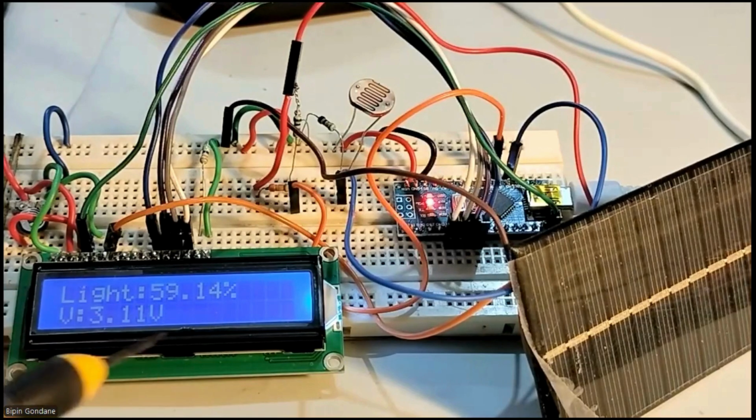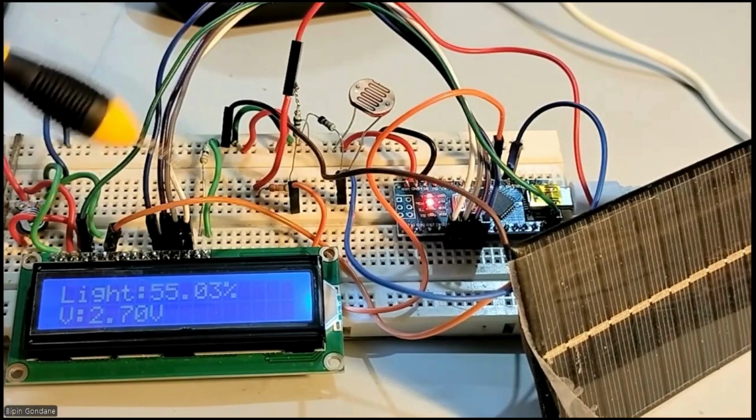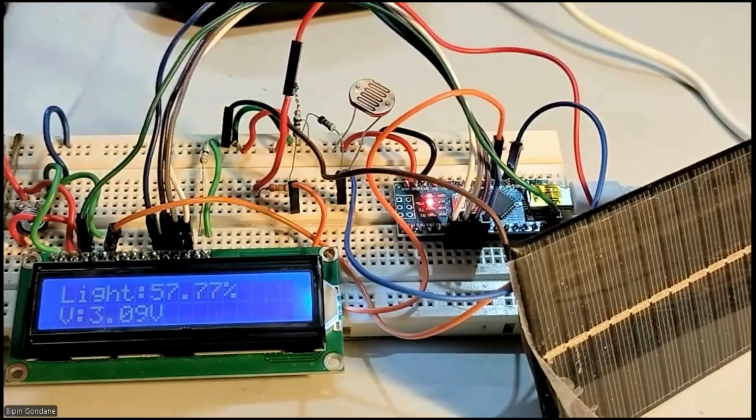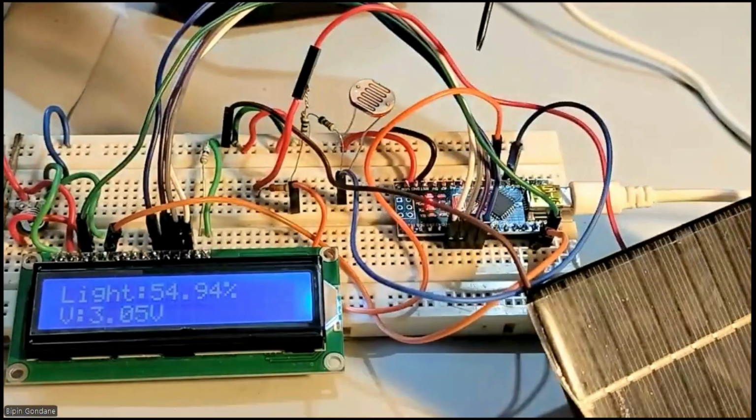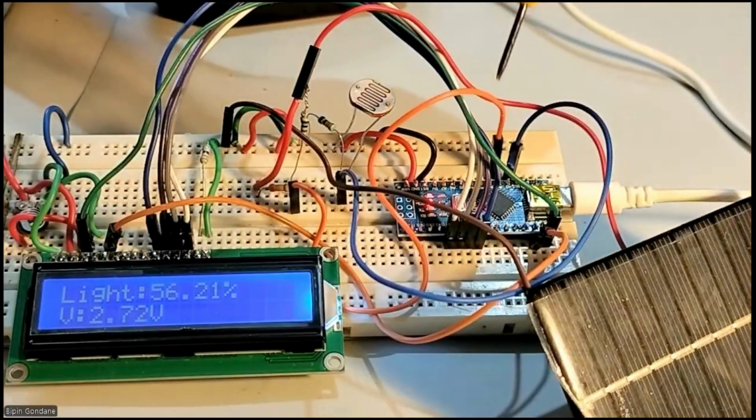Okay, this is my 16 cross 2 LCD with 16 pins. Pin number 1 is ground. Pin number 2 is supply, that is 5 volt. And the third is connected to the potentiometer center point, that is for controlling the contrast of the figures. RS and E are connected to pin number 11 and 12 of the Arduino. I have used an Arduino Nano over here. I will just try to show it to you. This is the Arduino Nano. You can use it also.